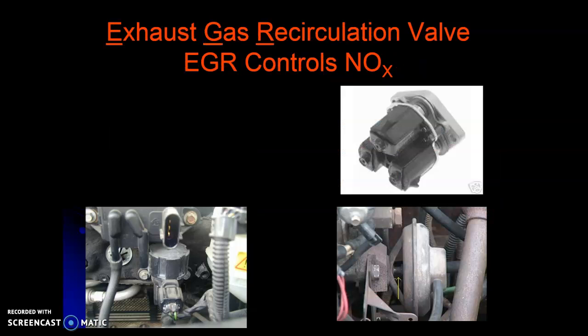EGRs, exhaust gas recirculation valve, talked a little bit about these. Basically, they're going to run inert exhaust gases into the intake manifold, lowering the displacement, lowering pressures and temperatures, lowering NOx. So you have a diaphragm style here, and this little vacuum is driven off of engine vacuum, and it pulls this plunger out and redirects air from the exhaust to the intake.